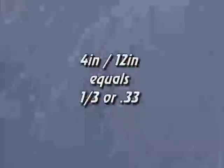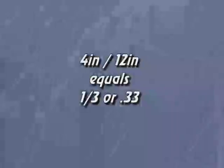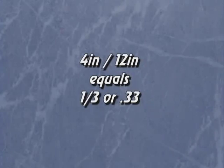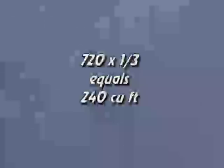To figure out the fraction of a foot we need to multiply by, we simply take 4 inches and put it over 12 inches and end up with a third, or 0.33. Now we take those two numbers, 720 and a third, and multiply them together. The answer is 240 cubic feet.